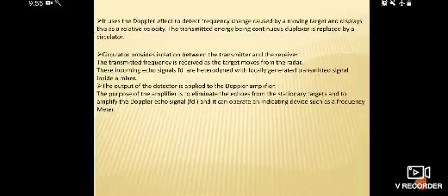It is to eliminate the echoes from stationary targets and to amplify the Doppler echo signals, that is fd. It can operate an indicating device such as a frequency meter. That means at the indicator side, we have a number of meters, and not only the display unit, we have a number of receiving sections at the receiver part. Okay, so this is the operation of a simple CW radar.